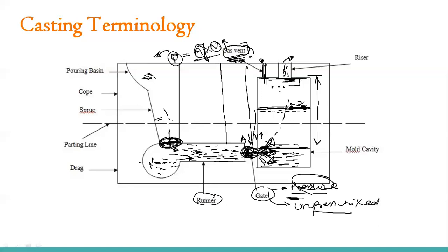So it has some less velocity, so it needed some time to fill up to this specific height. If this material is completely filled up to this specific height, then whatever the amount or the thickness of the molten material which is over here is the fresh liquid which is coming over from this gate at this position. So now this material starts solidifying.